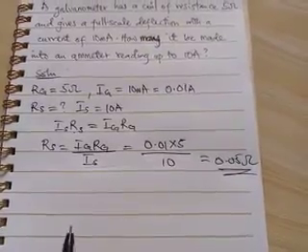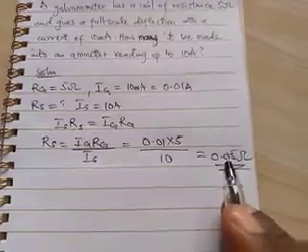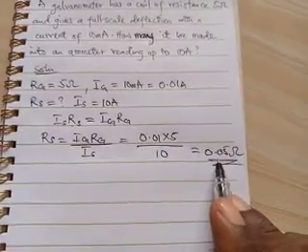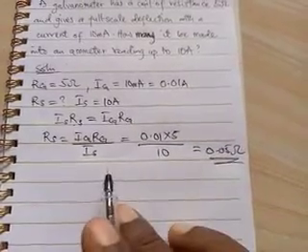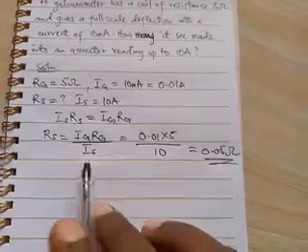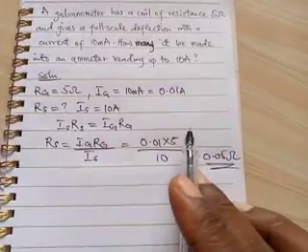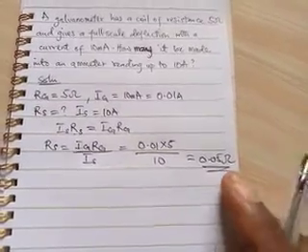So what it means is that the galvanometer must be provided with a shunt resistance of this value, such that 10 ampere passes through it and it is in parallel, and the current of 10 milliampere goes through that galvanometer and 10 ampere through the shunt.